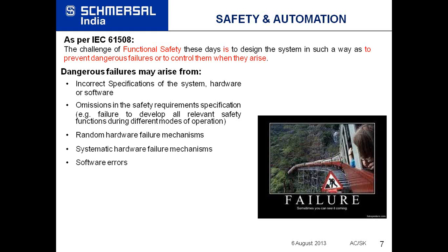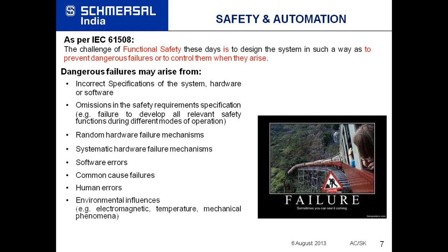which may occur because many equipments now are based on software, like a PLC or a drive. So there may be a software error which may lead to a dangerous failure. Then we can also have failures because of common cause, which are more related to human errors. Then we also have dangerous failures occurring because of environmental influences, like electromagnetic, temperature, or mechanical phenomena.